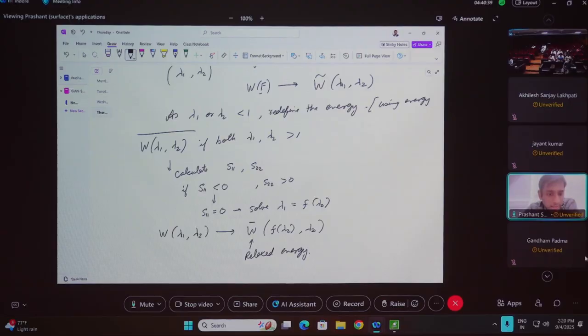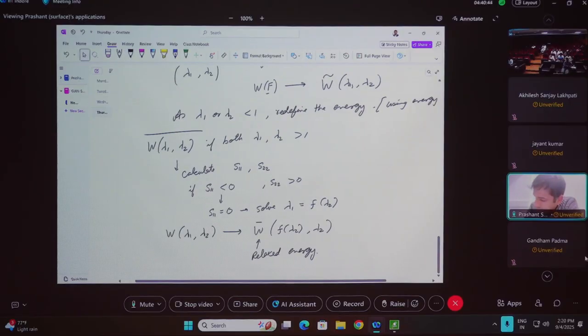Okay, so I'll recap this once more. This is the energy over here, which is what you would use in the usual sense, if all your calculations are going on normally. But at every loading step, as you are increasing the pressure in the membrane and calculating the solution, or if you're increasing the electric load and then calculating the solution, at every loading step, you need to keep a tab on the principal stresses in the two principal directions in the membrane.